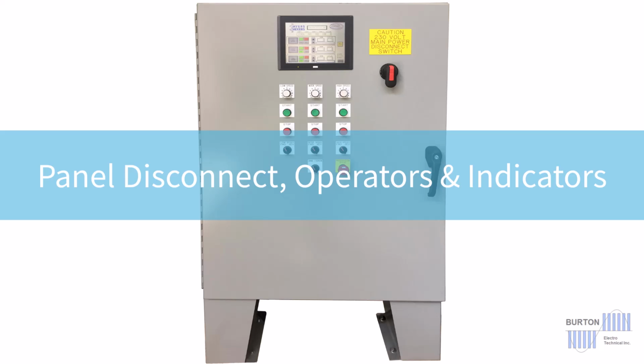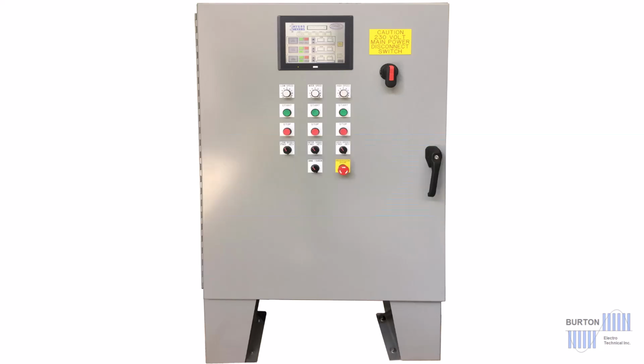Panel disconnect, operators, and indicators. Industrial control panels must have a means of disconnection from hazardous voltage potential. These devices are called isolation or disconnect switches. These switches can be locked in the off position. This prevents accidental energization of the panel.